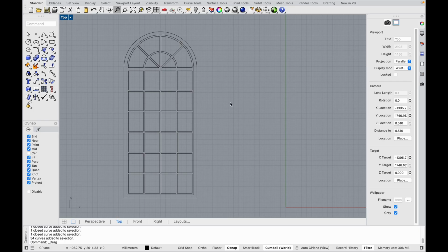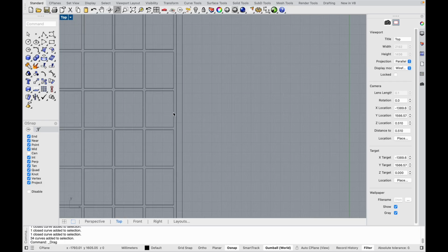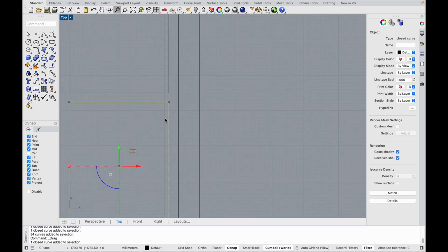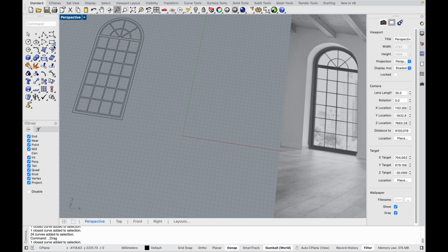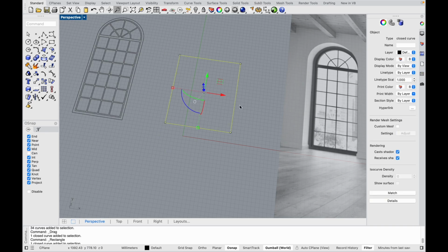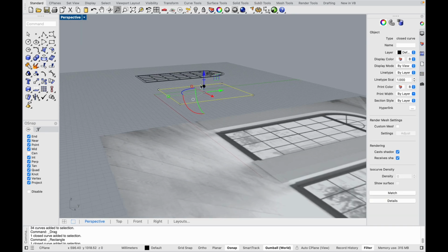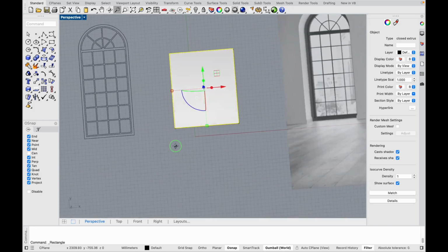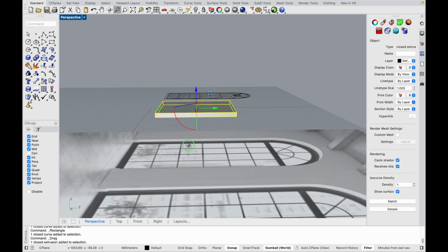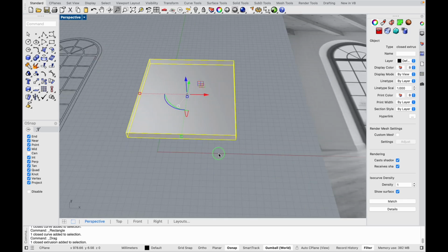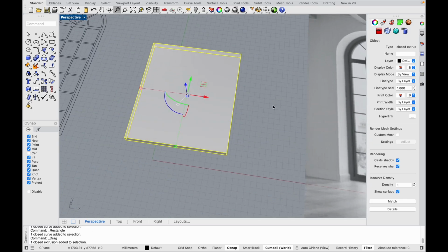With an extrude tool, and as I have said about the holes, it is really very, very important. So just for some example, we can draw some rectangle. Rectangle is a closed curve, closed continuous curve without holes, and we can extrude it with a gumball, and it will give us a closed extrusion. So the shape without holes, the shape which will look like a box.